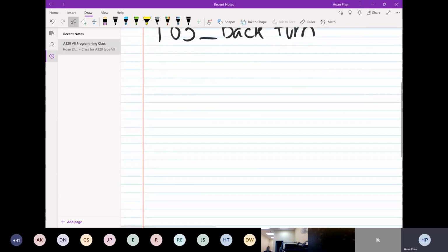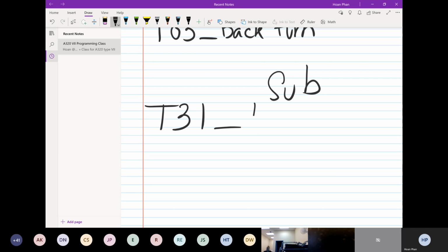We're moving on to the sub spindle. So for the sub spindle, in order to turn the OD, we're gonna use the left hand boring bar for this machine. And the reason why is you just flip the work coordinate system, and then the left hand boring bar is gonna face and turn just like the right hand OD turning tool on the main spindle. So we're gonna say, okay, the left hand boring bar we're gonna use and put it in tool 31. So left hand boring bar.